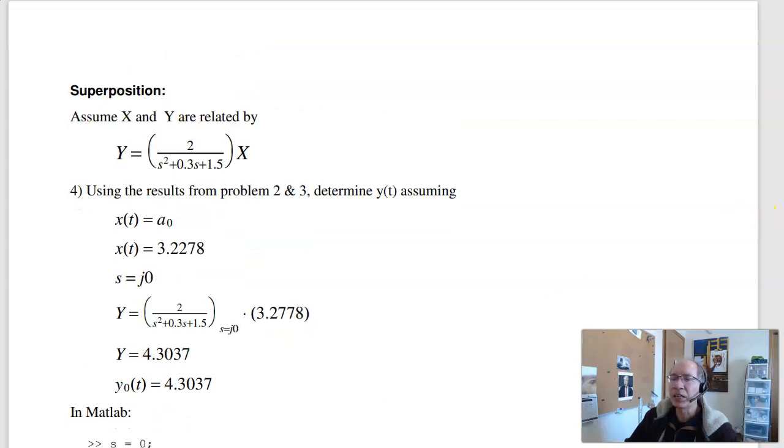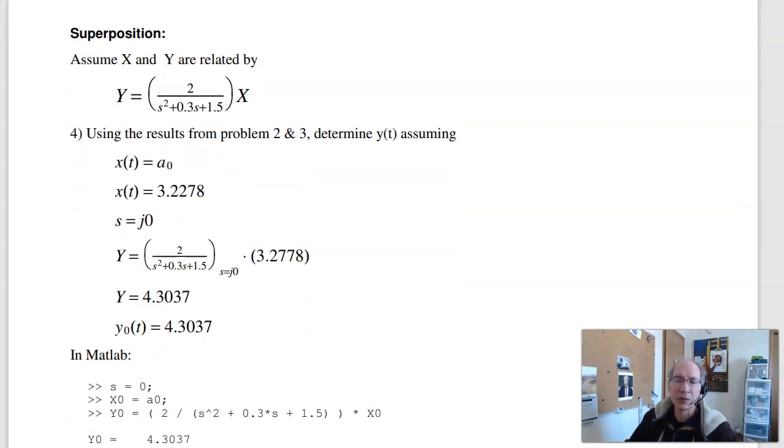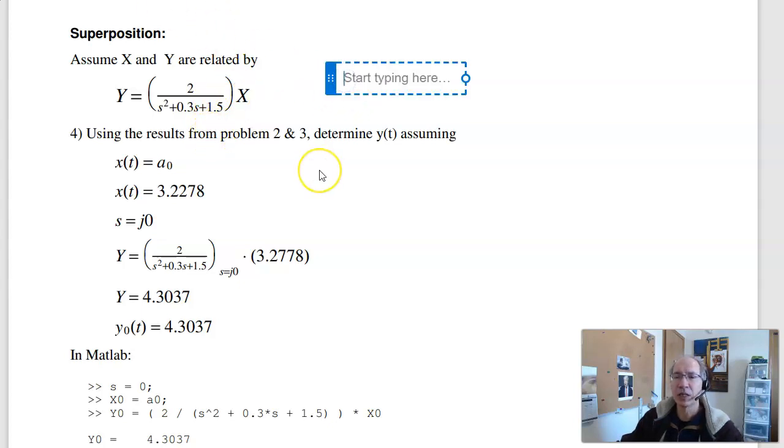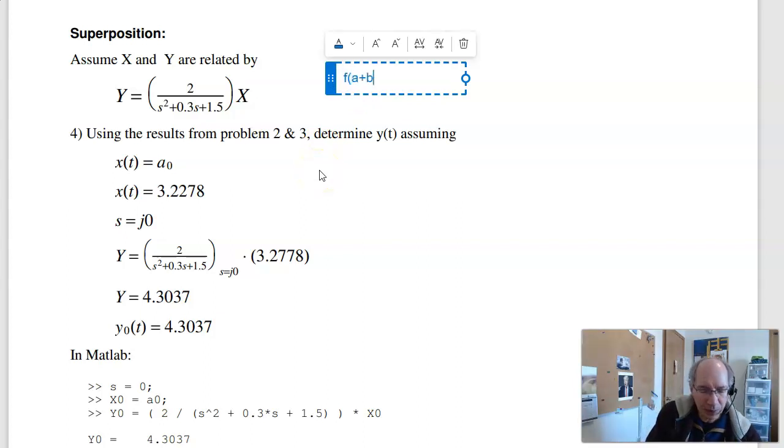The thing to take out of that is Fourier transform is just really curve fitting. There's no difference between curve fitting and Fourier transform, except I'm using a very special basis. The basis that I'm using is made up of sine and cosine terms because I know what to do with sines and cosines. So for example, suppose I have that periodic input hit with this filter. Find the output. Well, this is where we use the property of linearity and superposition. Linearity says that f of a plus b plus c is f of a plus f of b plus f of c.